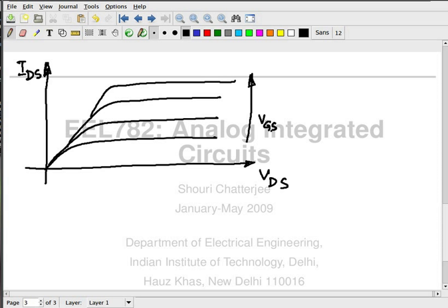First of all, it's intuitive why, between this curve and this curve, there is an increase in current. That's intuitive, right? Because the density of electrons in the channel has increased, so the current will naturally be more. There is more gate charge. Okay, so that we understand. We also probably intuitively understand the initial increase. Why does it increase?